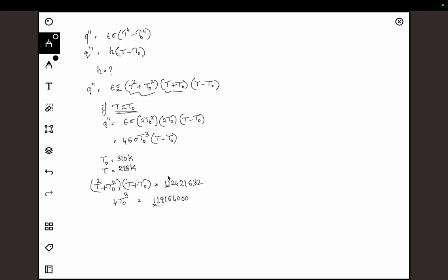So if you multiply this with sigma, which is again 5.67 into 10 power minus 8, most of these terms will actually go off, and you'll be left with only up to here, which is still accurate enough. So for most engineering scenarios where the temperature difference between the ambient and that particular surface is a little less, or the temperature itself is very low, in those scenarios you can do this.